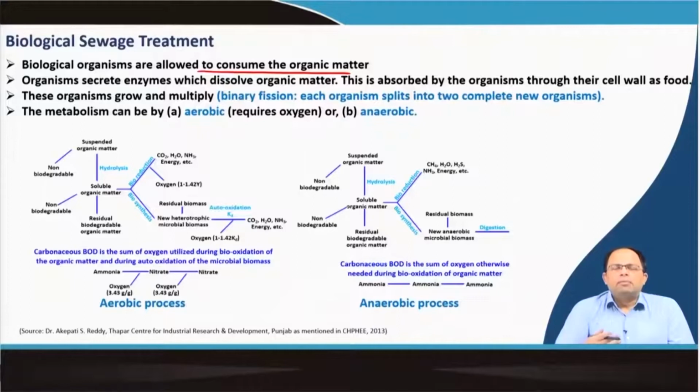Once that consumption is done, that means there is no food, and also because of the use of oxygen, the bacteria will actually die off. So, at one end we are reducing the organic loading, that means we are reducing the BOD, and the bacteria itself would be removed at the end of the treatment process.